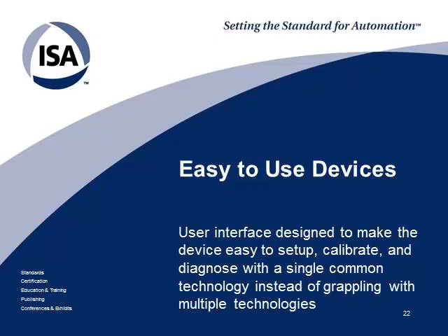I have been involved with device integration technology for, frankly, the last 10 or so years. Well, actually 16 years with the Fieldbus Foundation, but it was about 10 years ago that the Fieldbus Foundation, the PROFIBUS and Profinet organization, and the HART Communication Foundation got together to develop common extensions to what we call EDDL, Electronic Device Description Language. And this is nothing more than, as Ludwig said, those drivers that come along with your field device, so that in the end, when you plug your device in the network, you don't have to sit there and map registers to values and all that stuff.